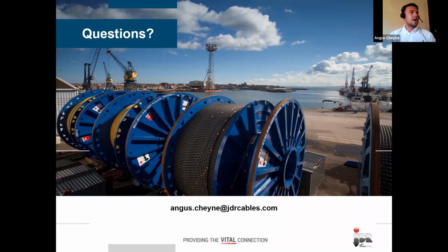Please say the acronyms for electrical cable covering when you can. We're looking at high density polyethylene for the outer sheath. For insulation material for medium voltage, that's cross-linked polyethylene. For low voltage, it's also cross-linked polyethylene, albeit for medium voltage, what we use is a water-tree retardant material.